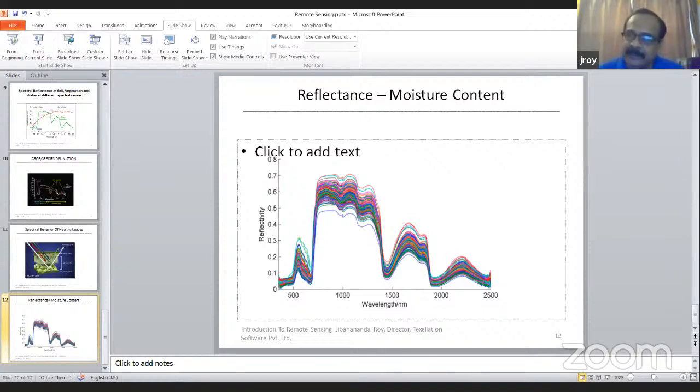Similarly, in satellite images, we take stereo images. How they're taken: either they will have two cameras, or the satellite on the next day, when it is visiting the nearby areas, will tilt the camera and take the image. But that is another kind of processing you require, because in stereo images, to properly find out your depth, you need both cameras to be parallel, which is impossible if we take on the next day. So that is the kind of processing we require.